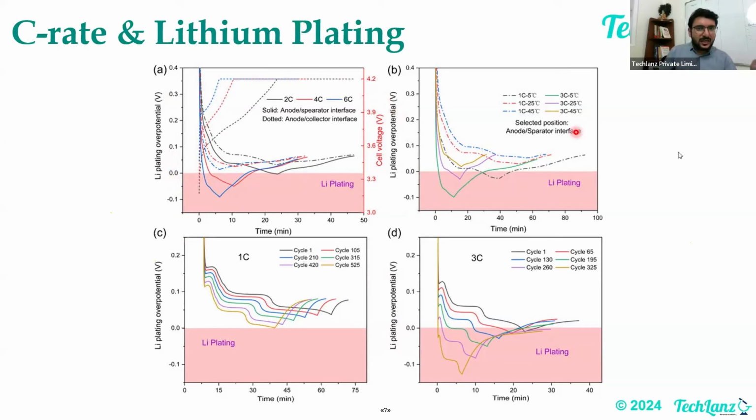If you design a charging algorithm only for a fresh battery pack, you are going to create thermal runaway issues, because the lithium plating potential is very high. Consider fast charging, like the CCS2 protocols, and now megawatt charging is also coming. If you design the battery pack charging algorithm based on the new battery pack, it's going to eventually fail in the field because you did not consider how the lithium plating potential changes with respect to time.